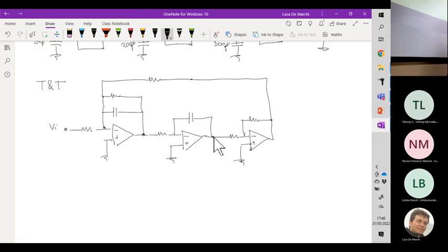It is important to pick up the output for the next stage here and not here if you want to keep the same phase alignment. Here you have -1 multiplication, while you may be interested in having same phase for input and output. So this is the low-pass output.